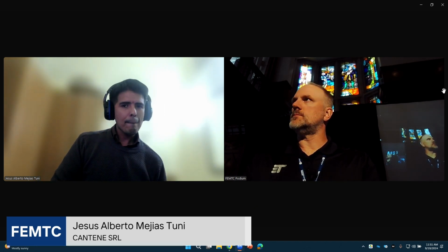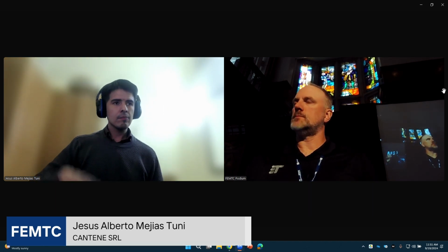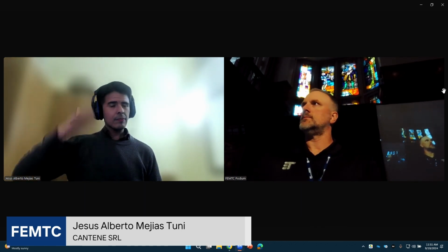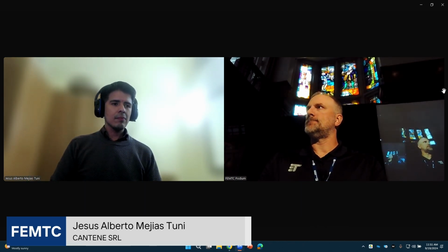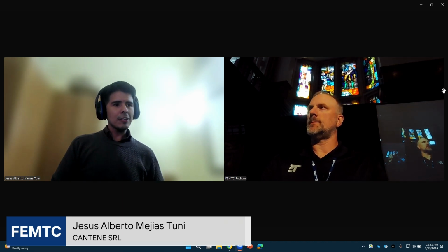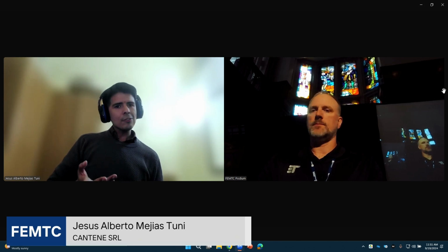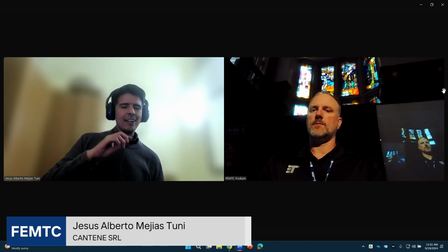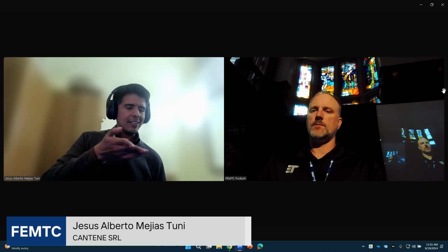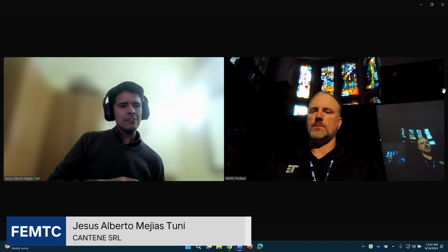Yeah, one of the ways that we estimated the roughness of the Memorial Tunnel was we looked at the volume flow through the tunnel, as you showed in your presentation, and we adjusted the roughness to match the volume flow in some of the experiments. It's not a perfect match, as you showed, but we had some idea of the roughness based on looking at the volume flow. Yeah, no, you also did the cold tests with the different amount of jet fans.